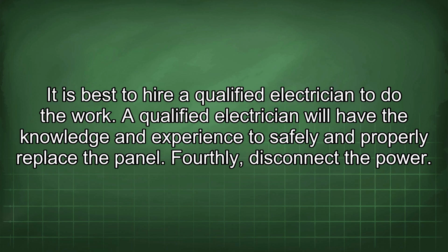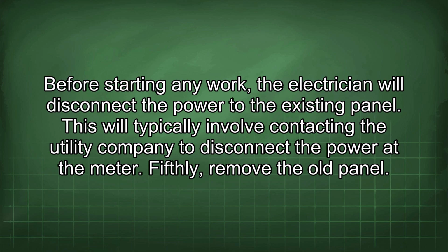Fourthly, disconnect the power. Before starting any work, the electrician will disconnect the power to the existing panel. This will typically involve contacting the utility company to disconnect the power at the meter.